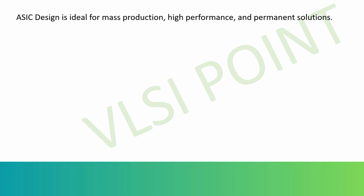Then foundry access, like TSMC, Samsung, Intel, for chip manufacturing. And yes, ASICs have a long development cycle, from months to a year. So use it when you want to produce millions of chips and need the best performance per watt, because ASIC design is very expensive and time-taking, and once it is fabricated you cannot change the functionality.